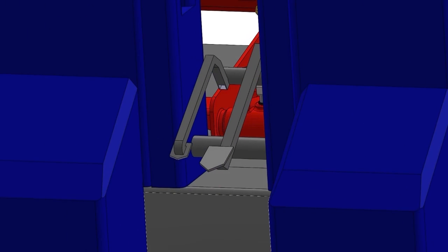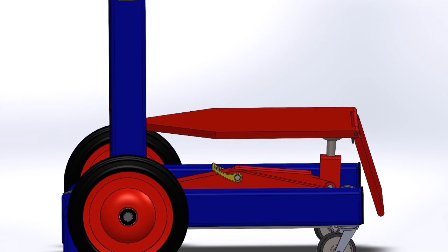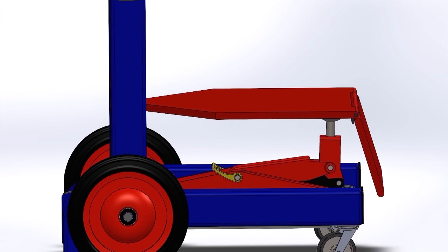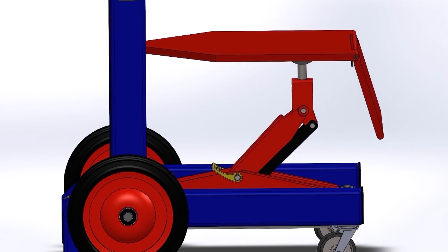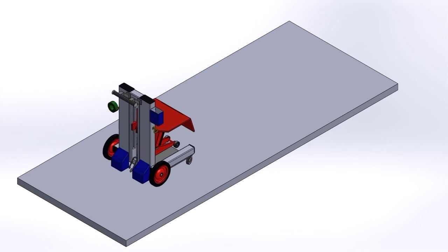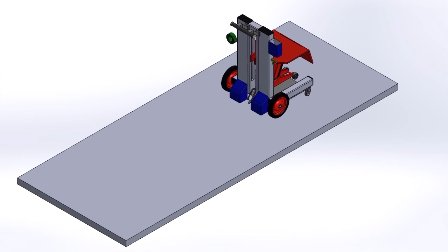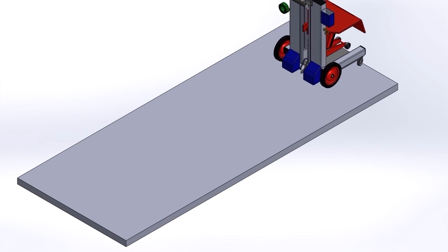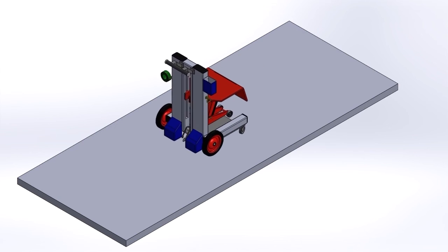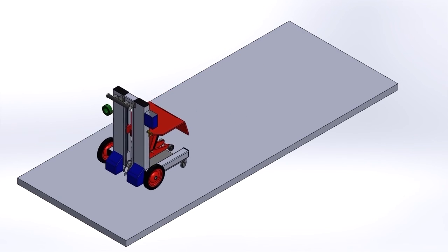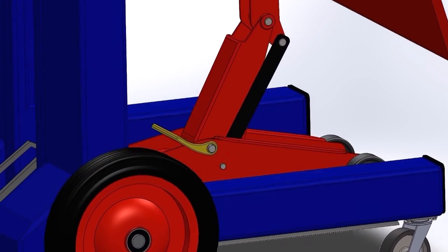To increase the height of the tray or to lift up loads, the right pedal will be used. After lift or place object according to the desired condition, the lifter can be moved front and back by using human force. To decrease or to lift down load, the left pedal will be used.